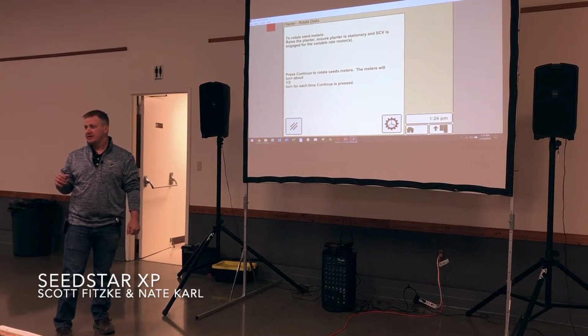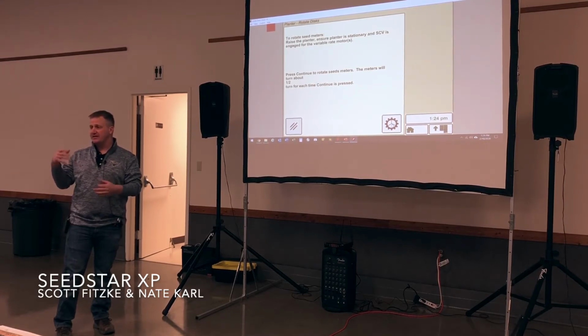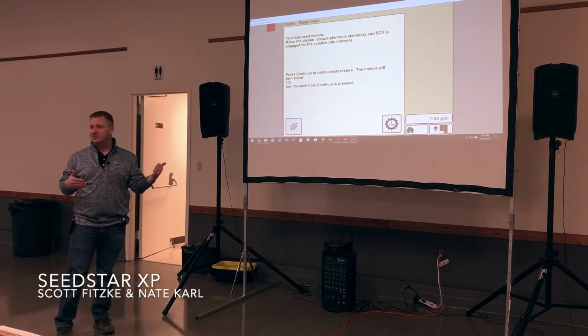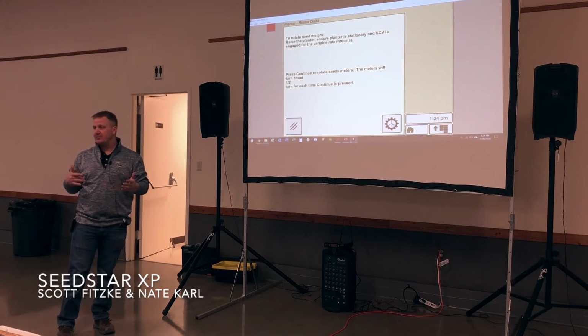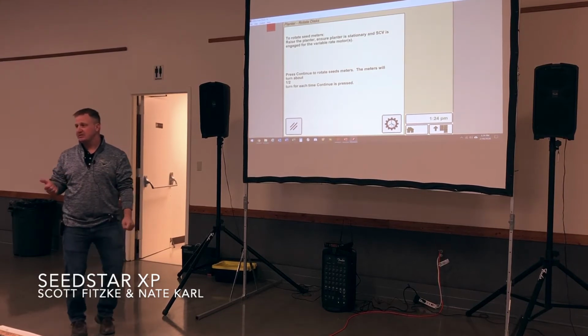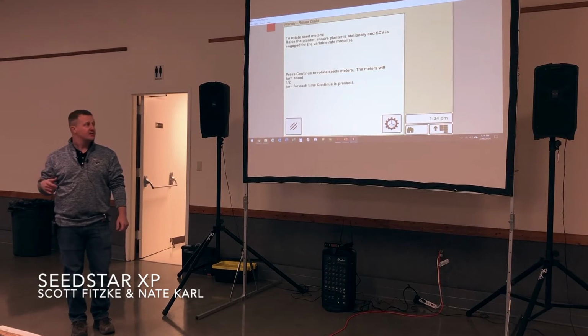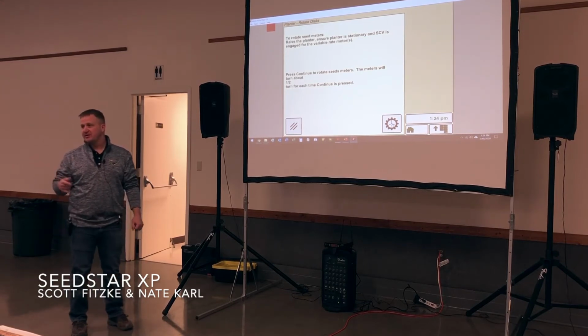1770. Okay, so a pull type. Yeah. It was probably the height sensor that's back, it's on the lift wheels. There's a linkage. The middle ones? Yeah, in the middle. Yeah, it'd be in the middle ones, and I'd tell you that that sensor was probably going bad. You could go check it. I doubt that it thought it was moving, because if you had radar or GPS, I'm sure it was because of the. So we'll go through some more of this where you can check that.